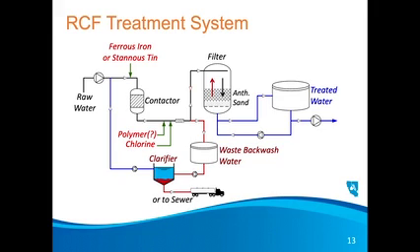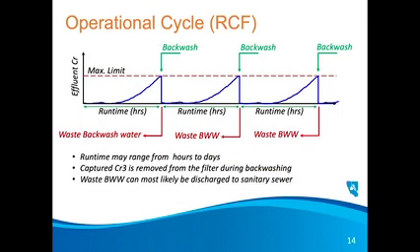It does generate a significant amount of backwash water, so it's always good to be able to recover some of that water through a settler and then dump the waste either off-site or to a sewer. Operationally, you're looking at hours of runtime, maybe more than a day, but it's a typical filter operation: you run water through it, you go through a backwash, you process the backwash water, and you go back into just cycling through the operations of the filter.